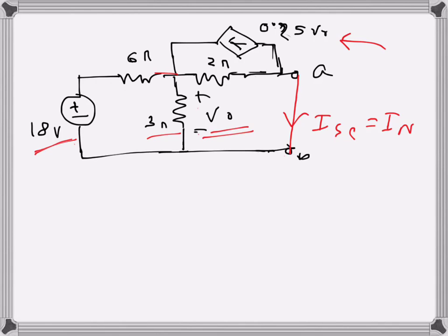So here there is a fixed voltage source, an independent voltage source with a series resistance, and I could think of converting it into a current source and a parallel resistance, and then these two resistances would come in parallel. They could be combined and then reconverted into a voltage source and series resistance, and that way I would get just one. I could get rid of this resistance basically, which I have done in some of the problems, but in this one I can't do that because this terminal I cannot touch. This one is a control voltage for this one. So I will try applying some other method.